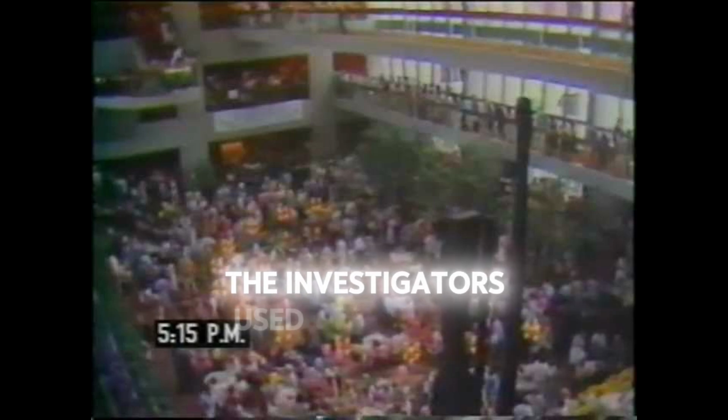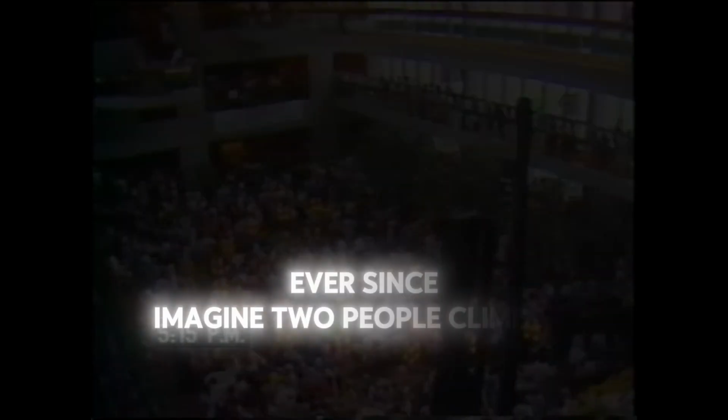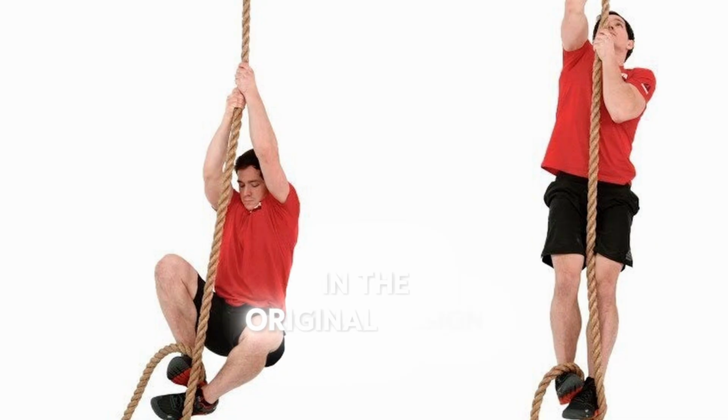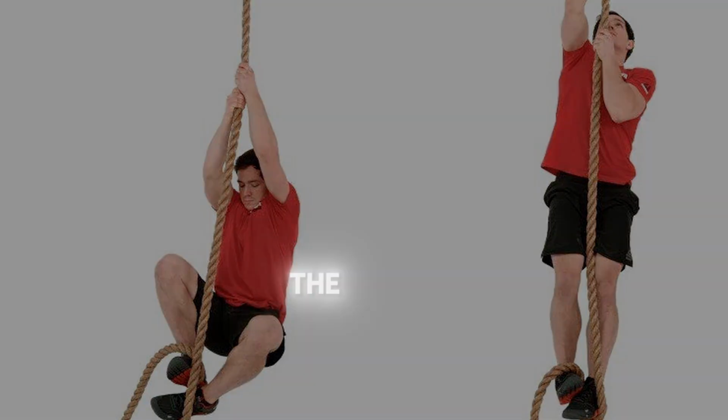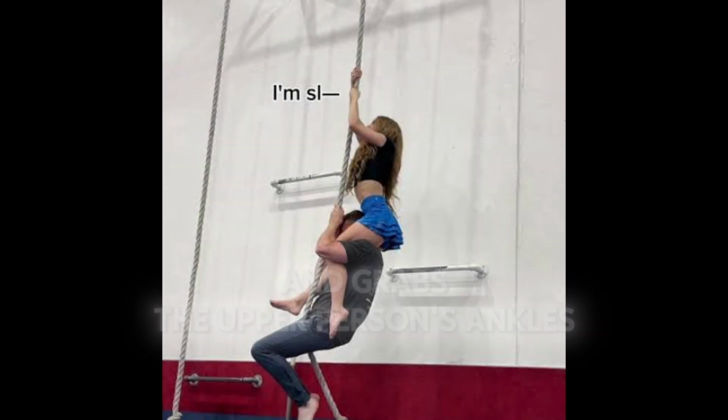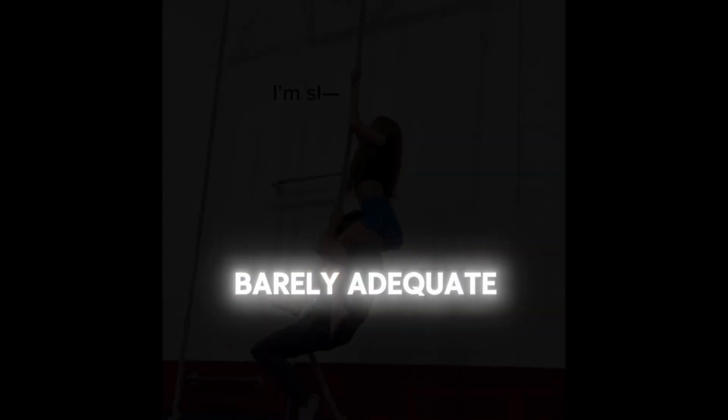The investigators used an analogy that has been taught in engineering schools ever since. Imagine two people climbing a rope. In the original design, each person grips the rope independently. Each supports only themselves. In the revised design, the lower person lets go of the rope and grabs the upper person's ankles. Nothing about the rope changed, but the upper person's grip now has to hold two people, and that grip was already barely adequate for one.